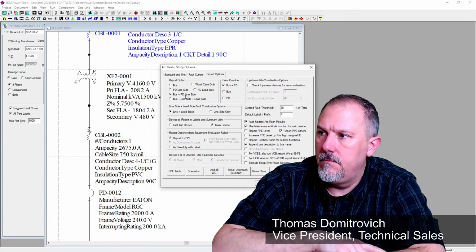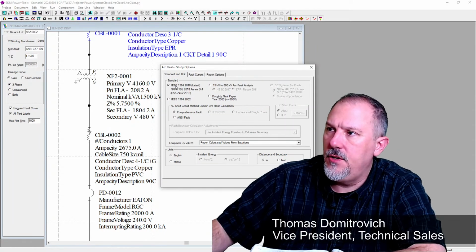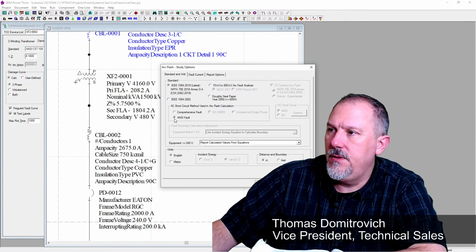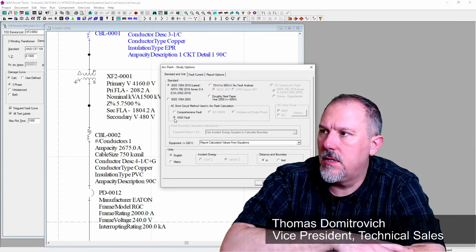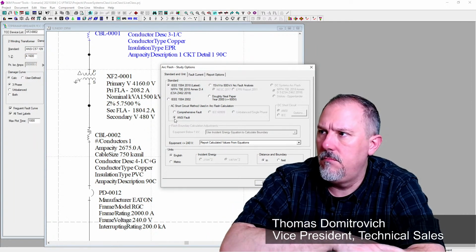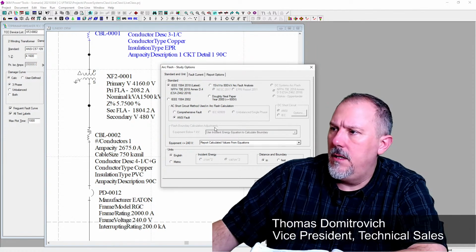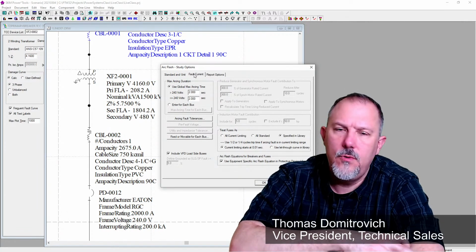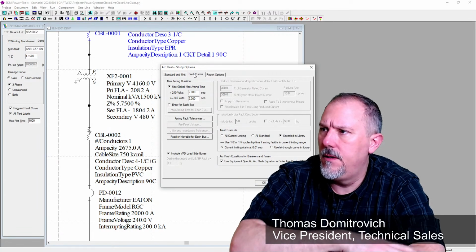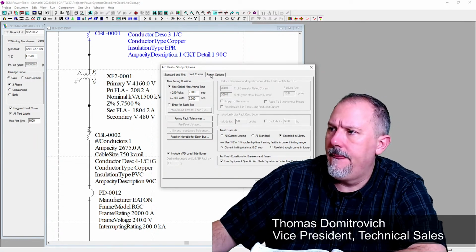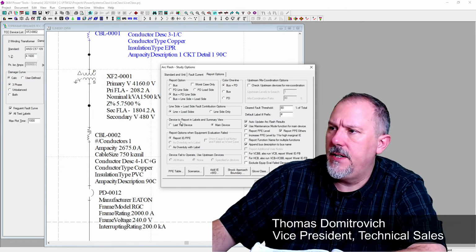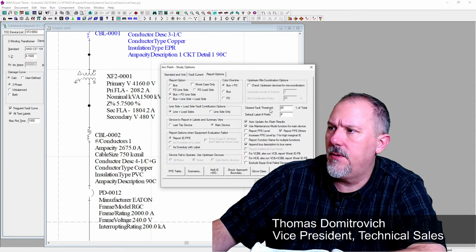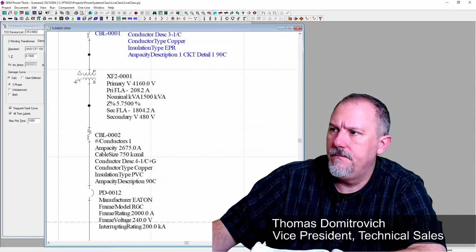I'm going to use 1584 2018. Do the ANSI fault, not the comprehensive. Let's see what else. Fault currents, use global max, so 2 second rule. I'll use the 2 second rule. And then this is where device to report in labels, main device, last trip device. I'm just going to run it. I have auto update cleared. So let's just run it.